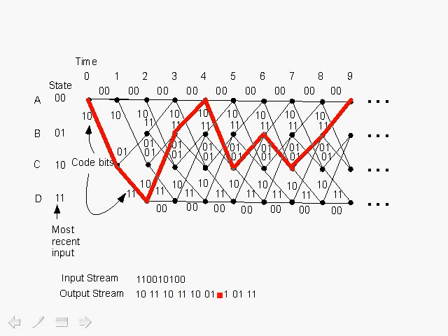Errors are made so that the received code is different than the transmitted code, and you have bit errors in the received code. And of course, using convolutional encoders, typically we use a Viterbi decoder to decode the convolutional encoder bit stream. The Viterbi decoder is a maximum likelihood decoder, which we'll get into, and has a great property in correcting random bit errors, not bursty errors. So typically in an additive white noise channel, errors are made randomly among the bits, and the Viterbi decoder would correct those random bits.